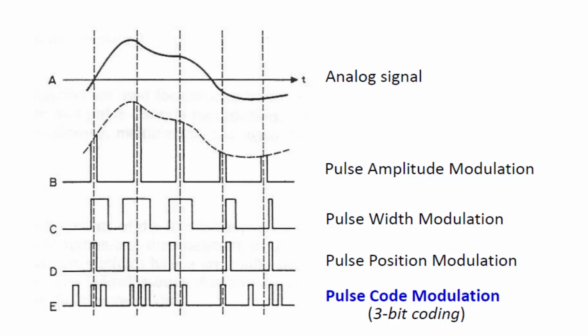In quantization, you allocate the quantized amplitudes to the actual sample amplitudes, and then every quantized amplitude will be given a code depending on the number of bits that you are trying to stack in one symbol period. So it will be an n-bit code. The n-bit code means it can be a 2-bit, 3-bit, 4-bit, and so on. If you are using a 2-bit code, there will be 4 quantization levels; with 3 bits, there will be 8 quantization levels, and so on.